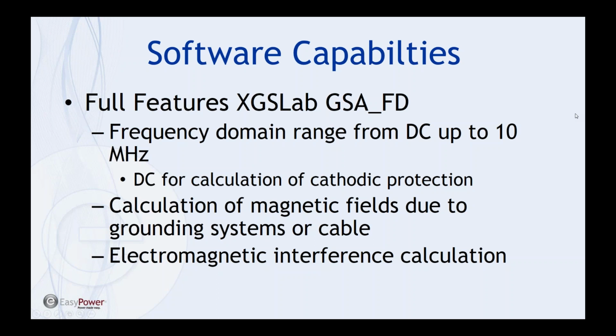Generally, these other facilities end up being buried pipelines or other buried electrodes nearby. But the fact that you can calculate the induced current and potential due to the resistive, capacitive, and inductive coupling is helpful in many situations.